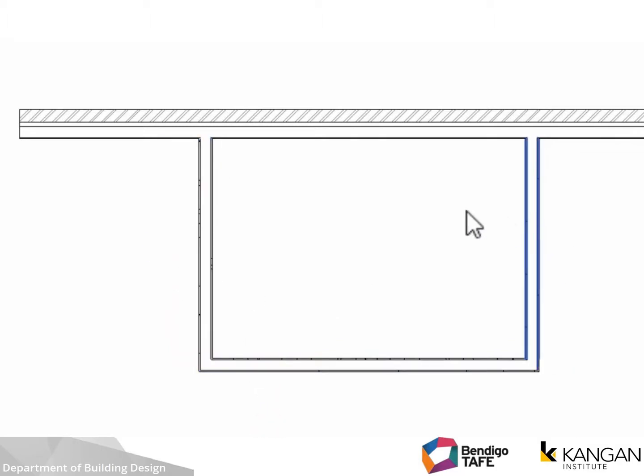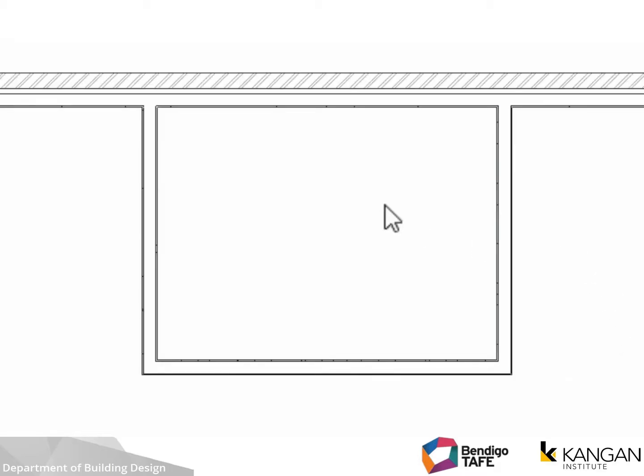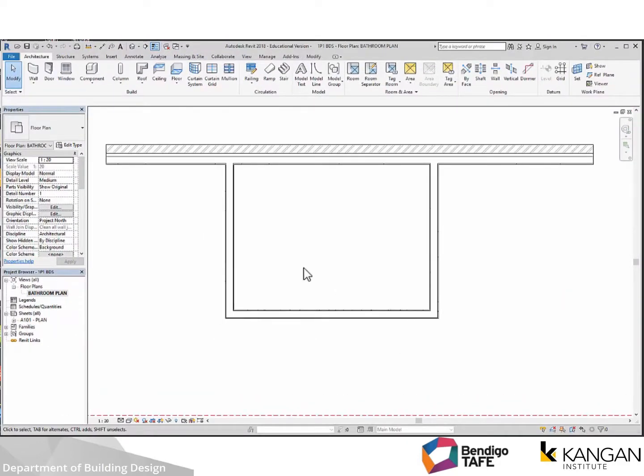I can then select on one of these two side walls, and that tells me the distance between this wall and the next one is 2600, and I need that to be 2450. So that's how we set up and put those walls in and at the right place. If the walls aren't exactly the same as your building, or you've got weatherboard walls, or it doesn't really matter, the objective is to draw your bathroom up, getting used to using Revit and playing with the interface.